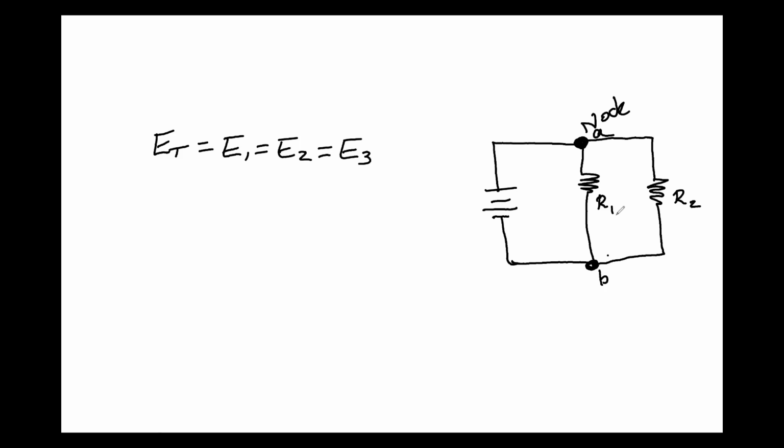Of course, the breakers protecting the branch circuits are going to be connected in series because you want them to be able to interrupt the current in case of an overcurrent situation. But in the case of the actual loads, all the loads are going to be connected in parallel. Why? Because of this characteristic that voltage remains the same in all the different branches.